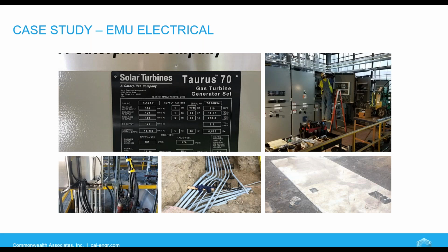Again, to the extent possible, new equipment was added prior to demoing the existing CTG and HRSG to minimize downtime with the final interconnects. So bottom right is the pad for the generator, and you can see all the electrical feeds are poking up there from the bottom to keep them away from public hands. In many campuses and industrial applications, you don't always know who will be around outdoor equipment, so you should always plan for the worst case scenario of an inquisitive passerby or someone who unfortunately may be a little more nefarious and want to intentionally damage something.